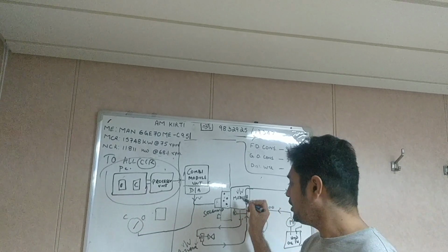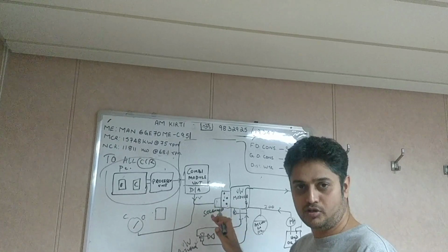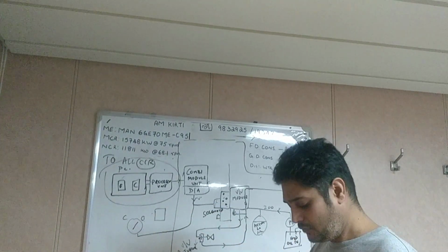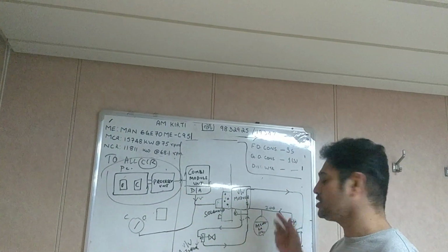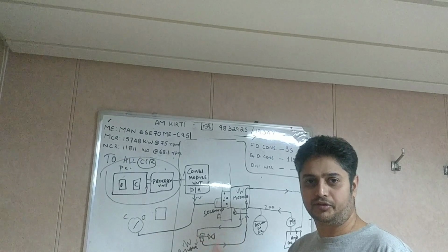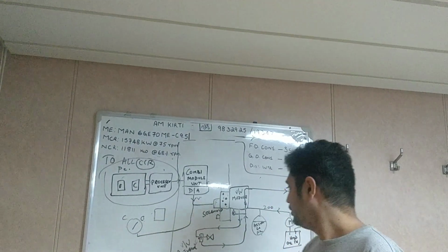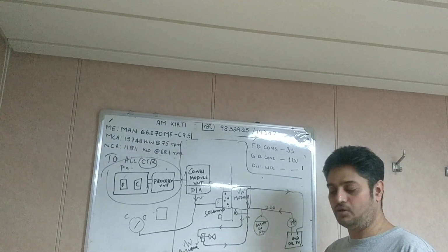Because pressurized oil is going inside the proportional valve and the valve cabinet, and the operation is also very quick. So for cushioning the system and to maintain the pressure, basically for both, we have the accumulator. This is just an overall idea of the system I am giving you.